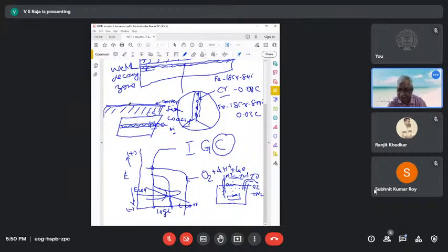It may slowly degrade. So what that means, suppose, for example, you take this conversion coating and put it in a salt spray test, which we also call the salt fog test. How long does it take to get red rust? You may get 300 hours, 400 hours, something like that. Suppose you apply a paint coating, it may take maybe 1,000 hours. Of course, it depends upon the paints, right?